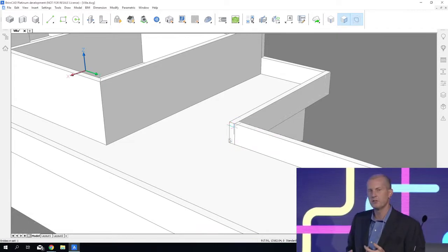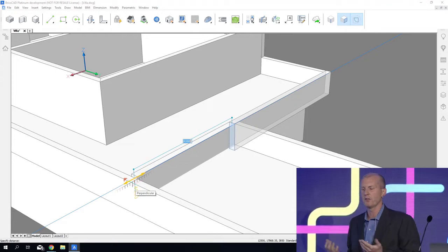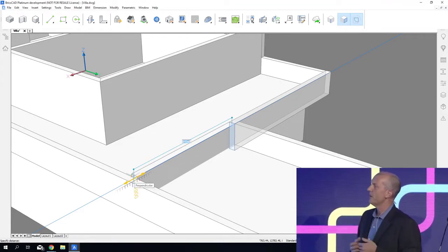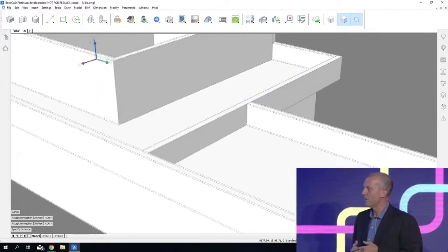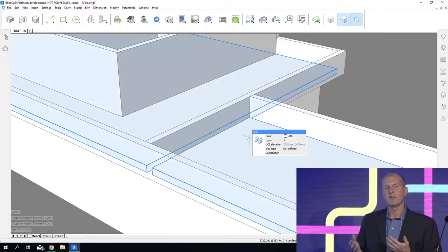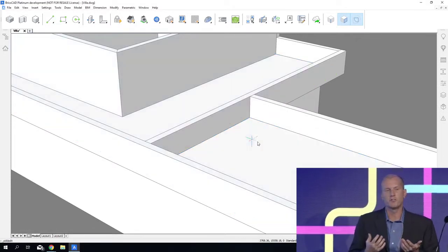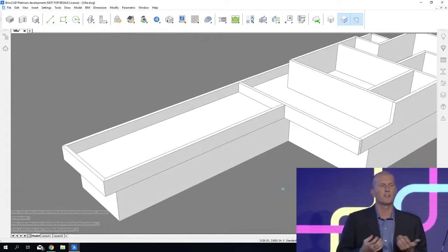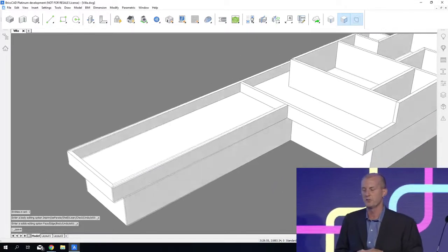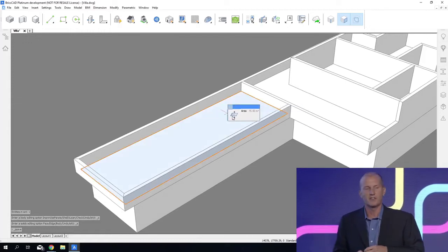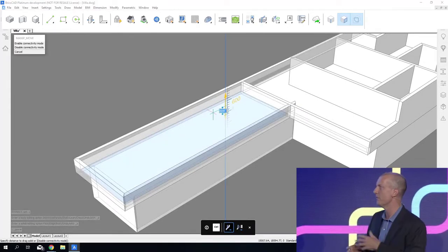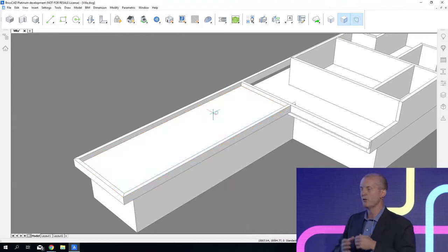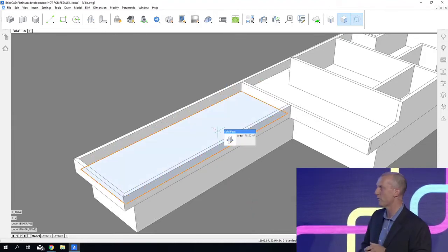There are multiple things that you can do at once when you start modeling with a tool such as this. By extending the wall, what we're actually doing is also splitting the slab into 2 separate members as well. And we can separate those, and then we can start to quickly work with them independently and use tools such as BIM drag to change the height of them and reposition them for something that we'll do a bit down the road when we start showing how Propagate works.